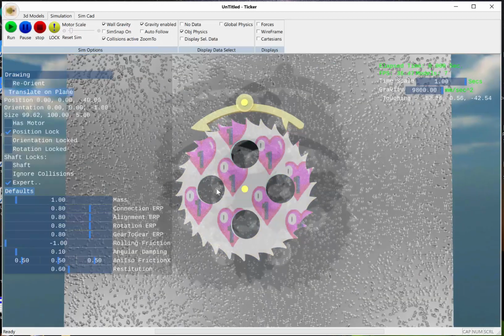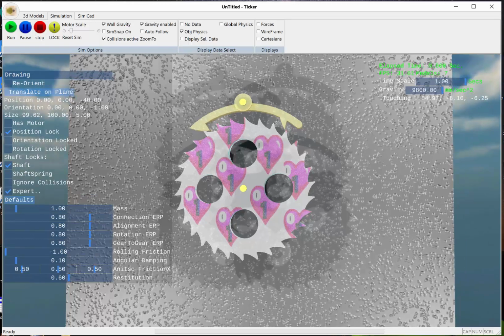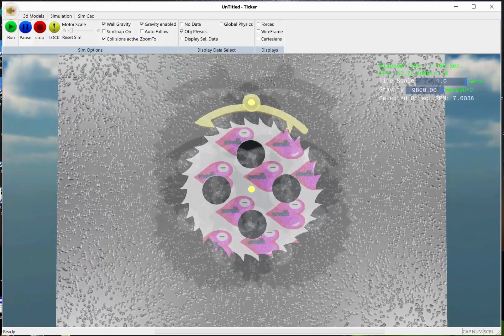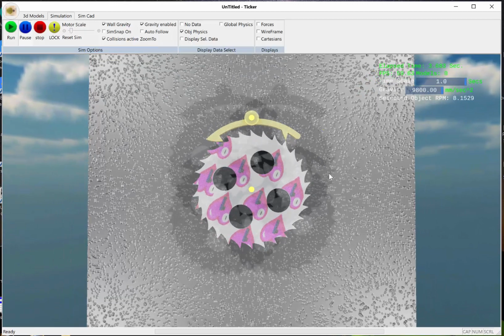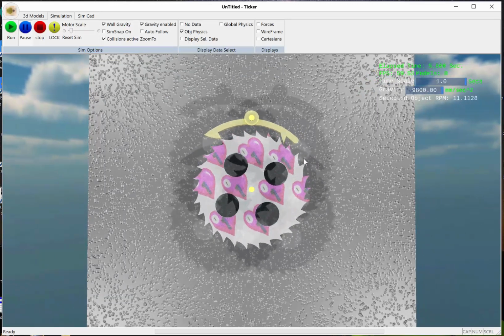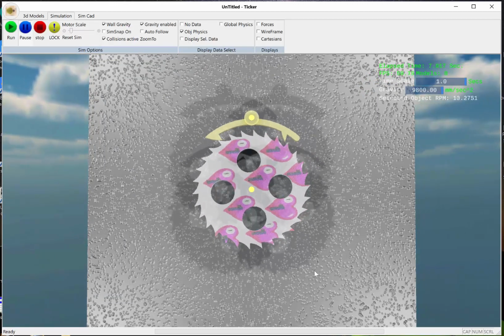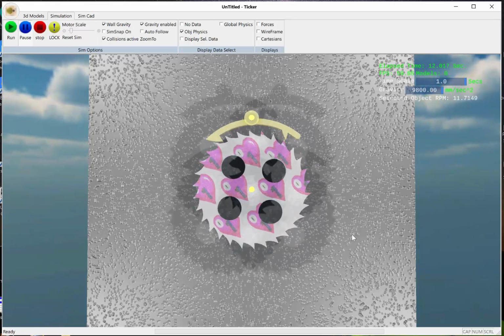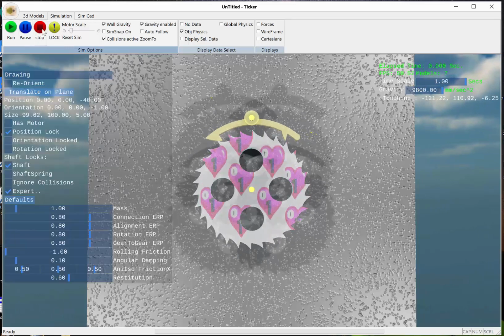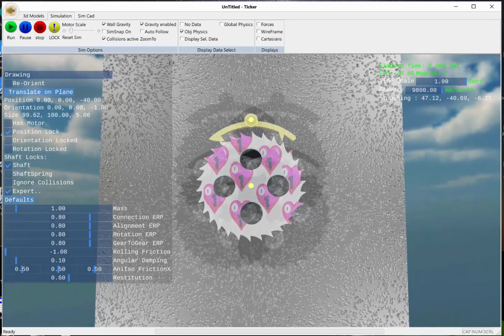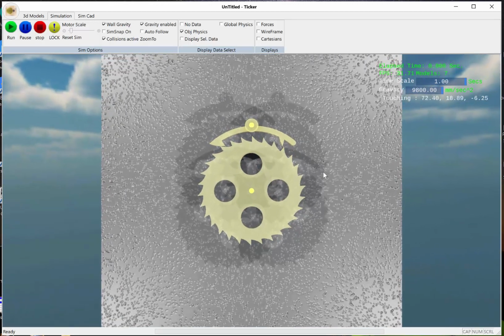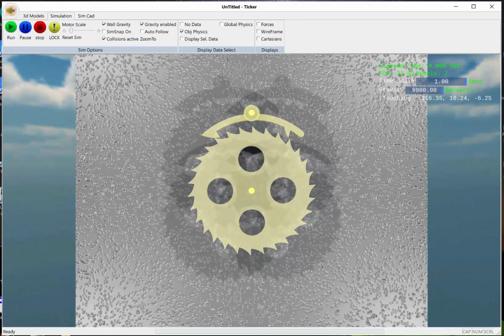So if we click on our ratchet, you can see there's a shaft lock here. We lock the grub screw for it. And now when we tell it to run, it does exactly what you get at home. It ratchets. It toggles back and forth very quickly. There's no gravity or pendulum to slow it down, but it's operating exactly as you would want an anchor escapement to run should you not have a pendulum on it. So that's the next thing that we really need to add: a pendulum.